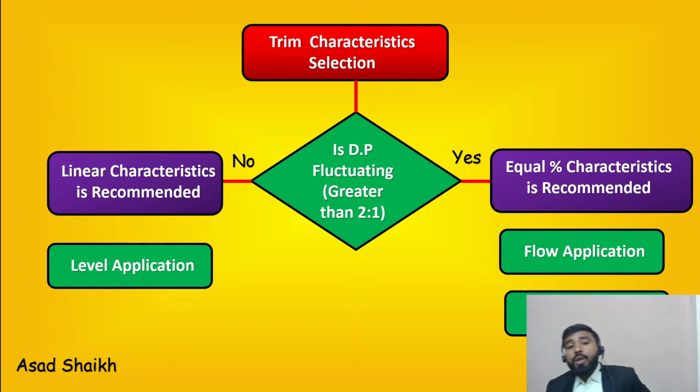Now here is one point: what if you specify an incorrect characteristic and you get to the plant? Because of the latest positioners which have come in the market, you can still modify the characteristic if they are configured correctly. So if your characteristic selection is not that accurate, you can still find a solution. However, relying on the positioner to make your characteristics is not a good option. Try to keep your plug and your cage designed in the correct characteristics. That should hopefully be more helpful to you.